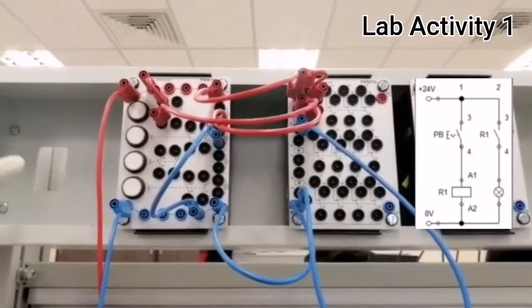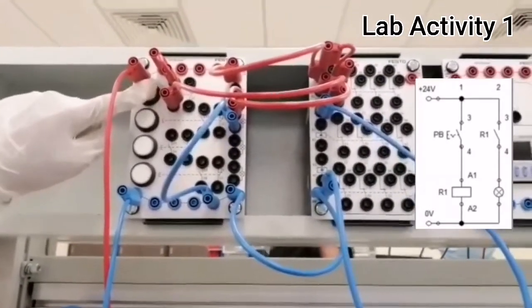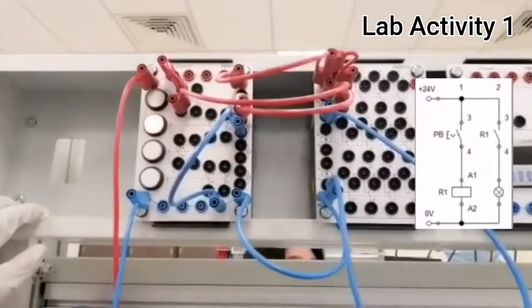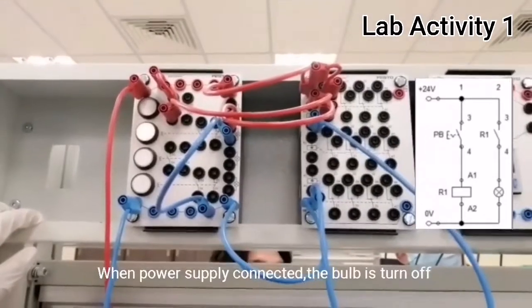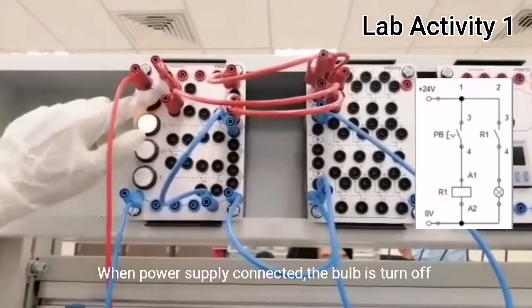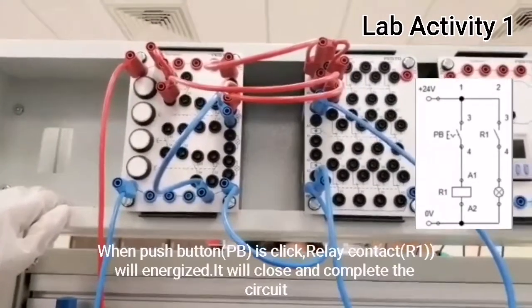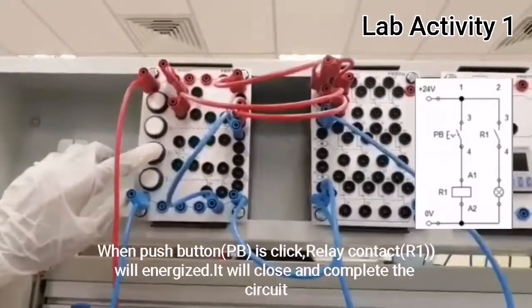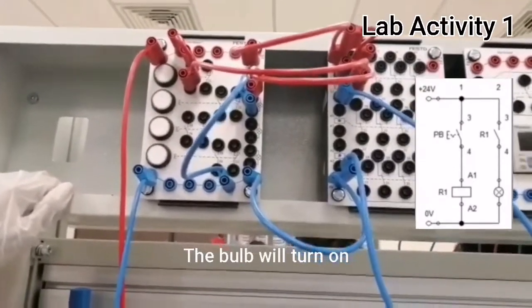Okay, let's go to the lab activity 1. Task number 1A. As you can see, we refer to the circuit. When the power supply is connected, the bulb is turned off. When the push button PB is clicked, relay contact R1 will energize. It will close and complete the circuit. The bulb will turn on.